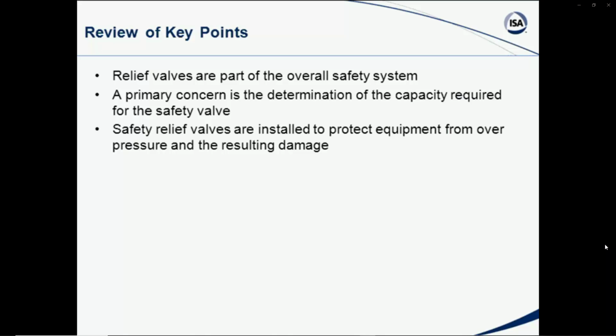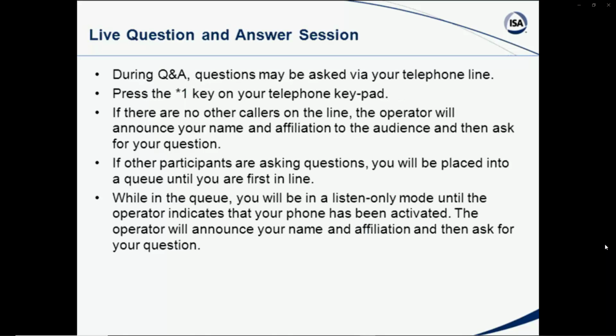Also, don't put the shutoff valves underneath it, though, unless you do have a protection process or setup that takes care of that. Because what we're trying to do with any of these situations, of course, is that safety relief valves are installed to protect equipment from overpressure and the resulting damage, loss of life, environmental impact, anything like that. That's what a safety relief valve is. For when something bad can happen, this is one of your lines of defense as far as your safety system is concerned.